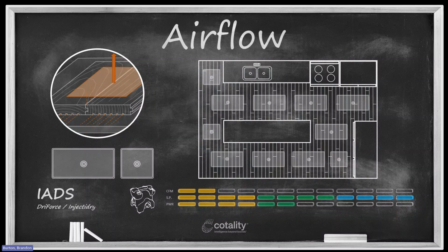Now that distance that you want to leave between these mats is going to vary, and I'll give you some pointers on what I've experienced for what that distance should be. If I am dealing with a water damaged floor that was finished on site, so boards that were installed without any finish on them and then sanded and finished on site, that finish is going to be a much greater seal on that floor than a floor that was pre-finished. A pre-finished floor is a floor where you buy it and the finish is already on the boards. Then you install that tongue and groove assembly and apply no additional finish. That flooring is going to allow for more airflow between the boards.